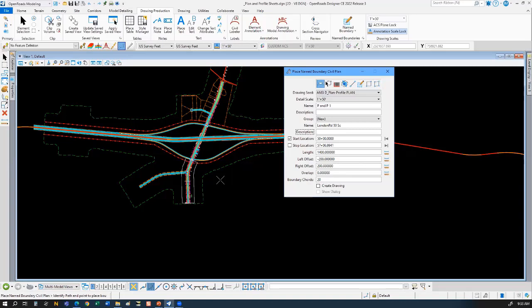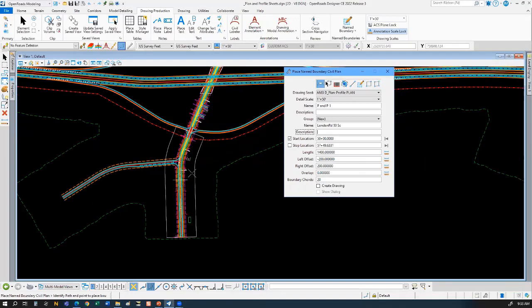So you can actually change those numbers if you want, but what I don't recommend is going any larger than the total distance that is shown here from the seed. So in other words, don't go any longer than 1,400 feet, and don't go any wider or taller than 400 feet.